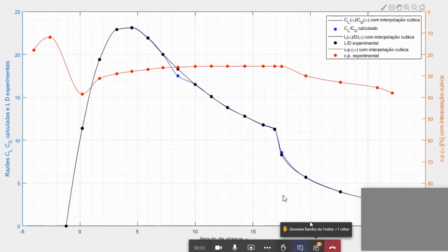Yes, you know what? Sometimes it's even acceptable to make just a linear function, just lines between points. Because this kind of approximation, when we go to second order, third order, and fourth order, like for this spline, for example, always linearizes the solution. And real aerodynamic processes are not so simple and not linear, so they do not go according to the spline function. It's even good to put just straight lines between points, and then it's acceptable.